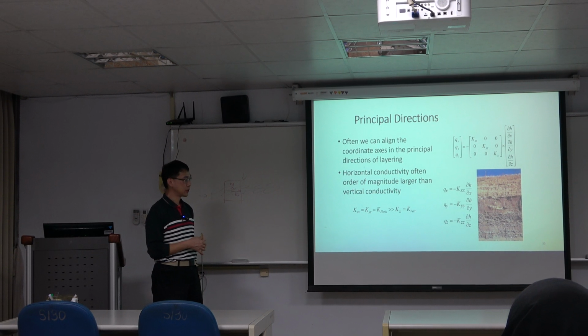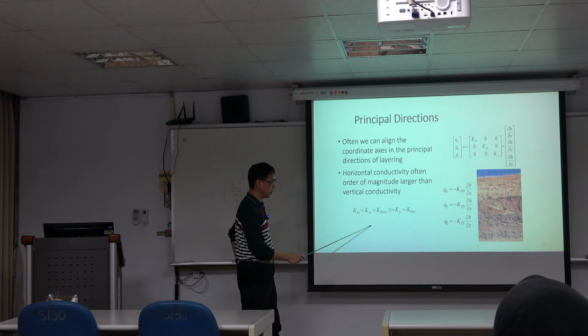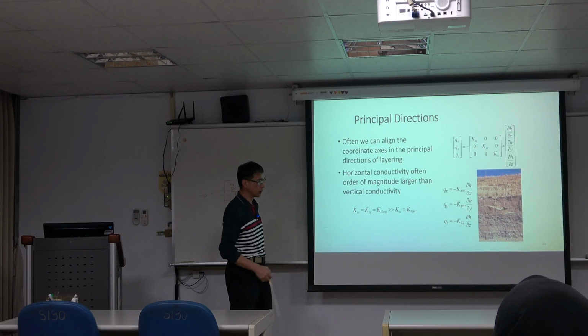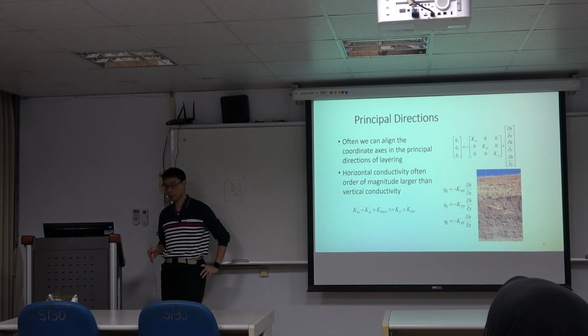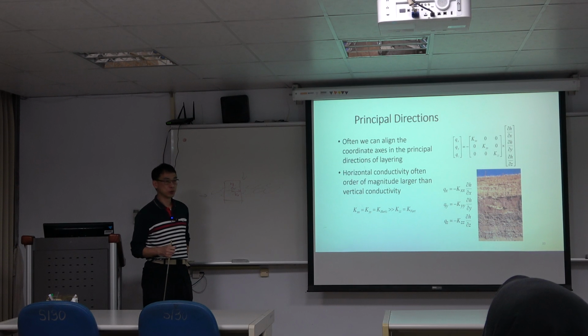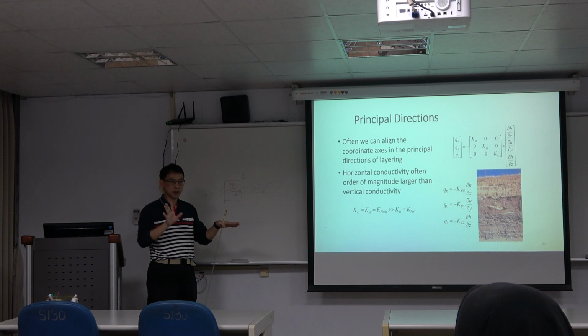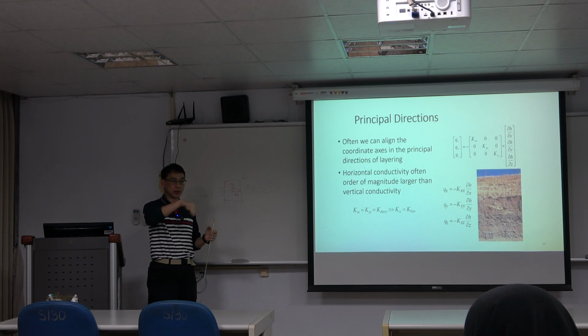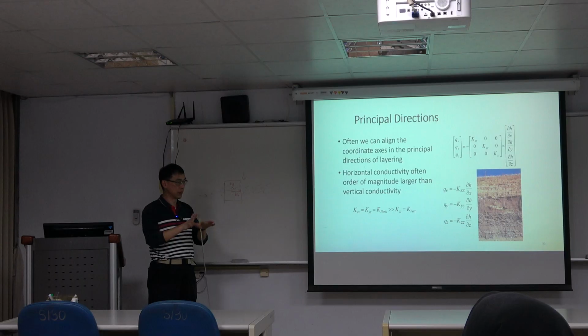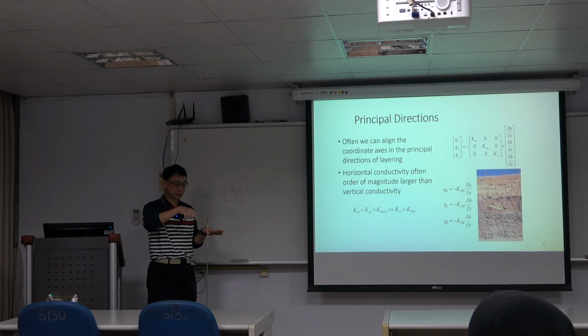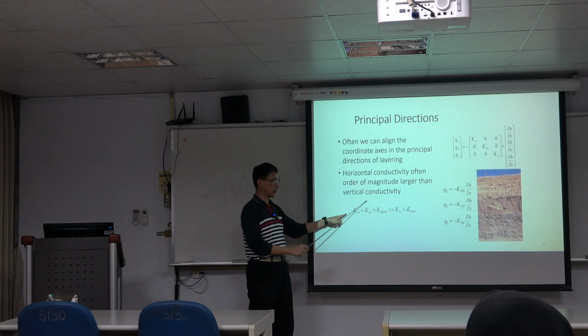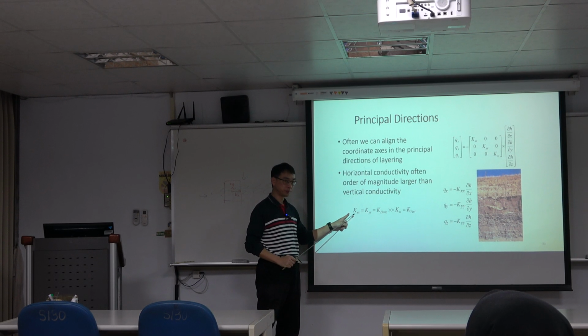And this depends on the parameters obtainable, because when we would like to obtain the K values, we commonly use the pumping test. And when you do the pumping test, we assume the radial directions, okay, a cylindrical coordinate system. So in the radial directions, we assume they are homogeneous. We use the ideal case. So we are not able to separate Kx and Ky, because they are the same in the horizontal directions. So this assumption is based on our Theis solution.